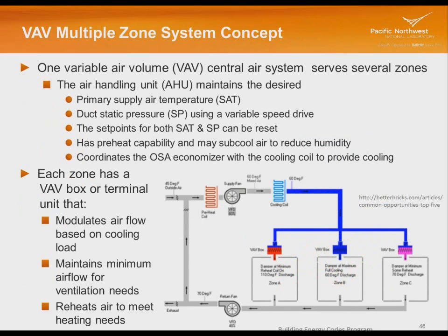So let's talk about variable air volume, which is one of the more popular types of systems in larger buildings, especially office buildings. So again, we've got our secondary unit up on the roof. We've talked about that. It's got the mixing section. It might heat the air. If it's really cold outside, it would cool it down when it needs to. So let's say I've got 60-degree air coming out of this unit, and I've got the same primary air going to all of my zones.